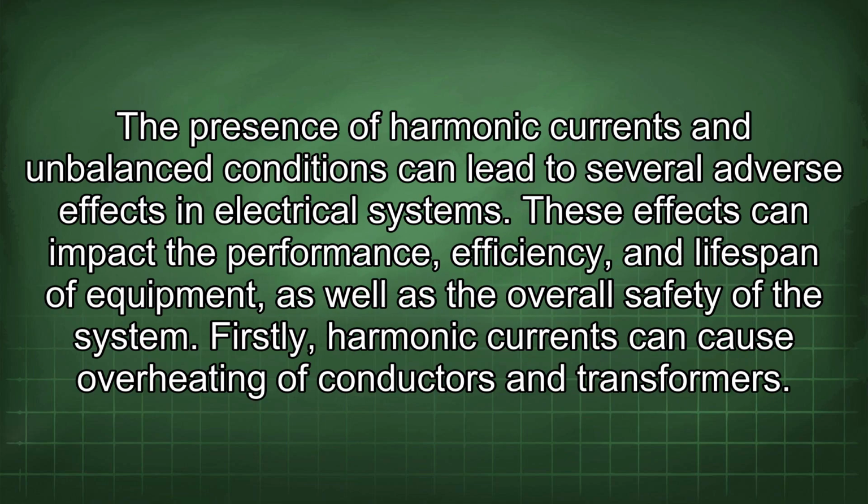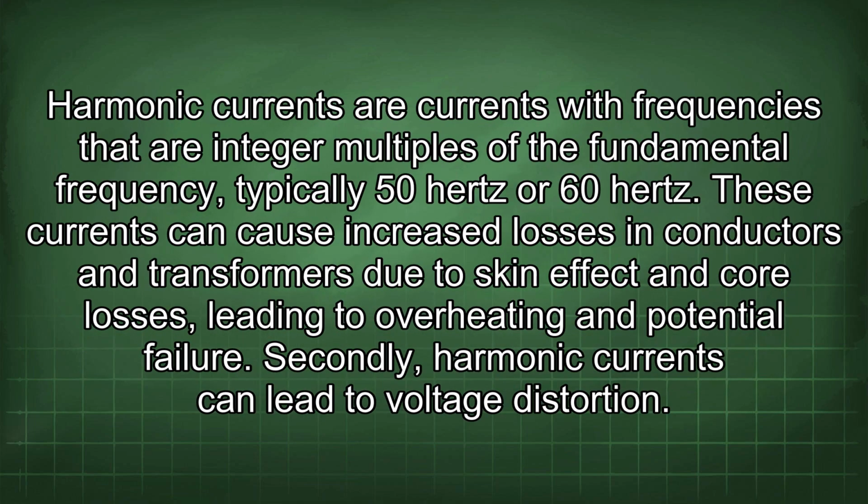The presence of harmonic currents and unbalanced conditions can lead to several adverse effects in electrical systems. These effects can impact the performance, efficiency, and lifespan of equipment, as well as the overall safety of the system. Firstly, harmonic currents can cause overheating of conductors and transformers. Harmonic currents are currents with frequencies that are integer multiples of the fundamental frequency, typically 50 Hz or 60 Hz. These currents can cause increased losses in conductors and transformers due to skin effect and core losses, leading to overheating